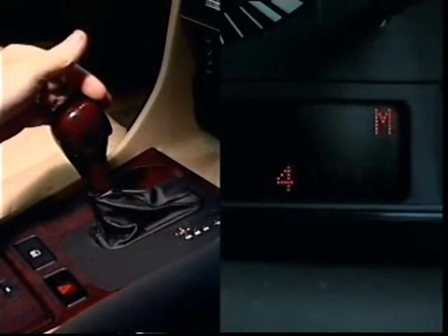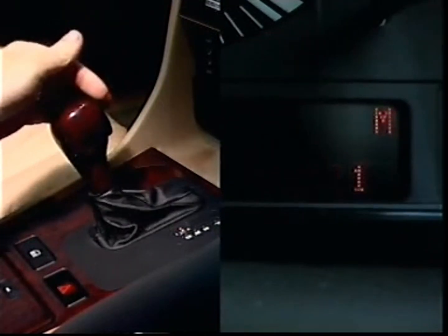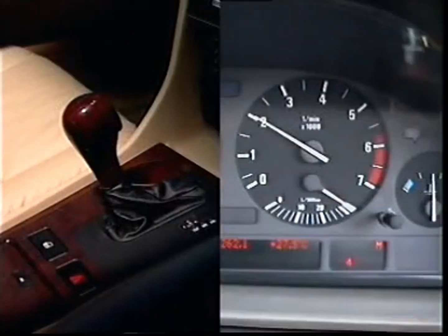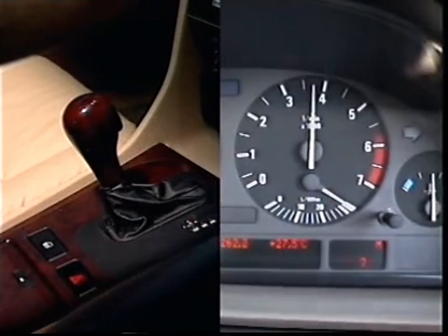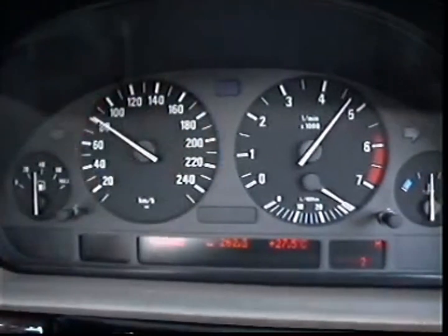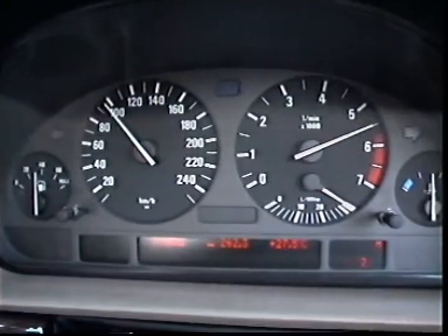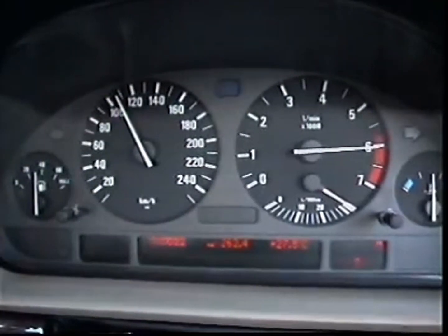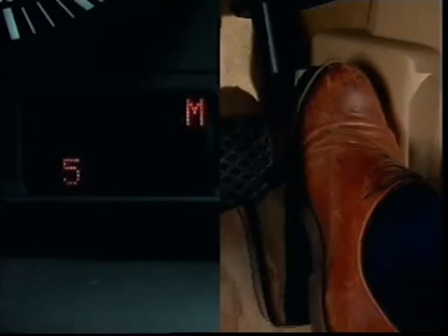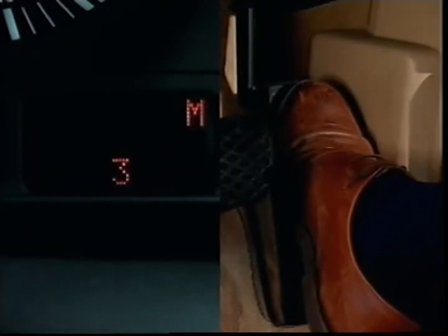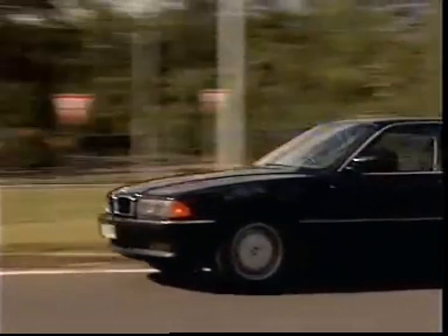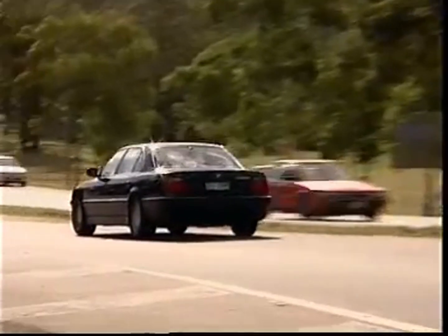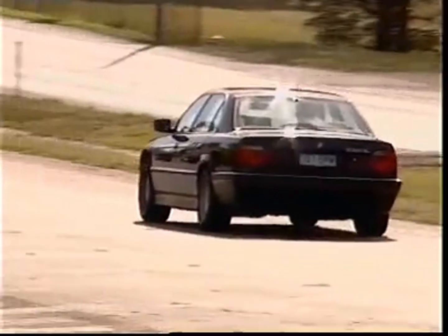Overspeed protection prevents a gear engagement lower than the governed engine speed. And when a low ratio is selected for acceleration, a shift up to the next higher gear takes place shortly before the governed speed is reached. Kick down initiates downshifts in all speeds to the lowest available ratio. And at low speeds, automatic downshifts as far as third gear occur to ensure adequate traction for reacceleration.